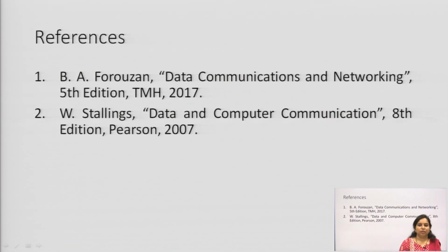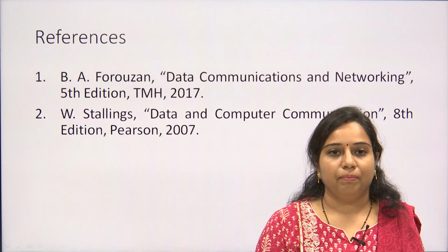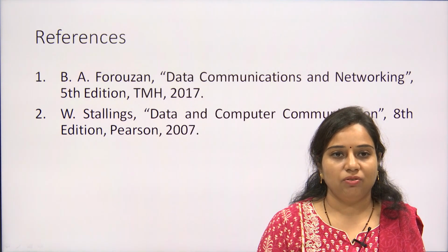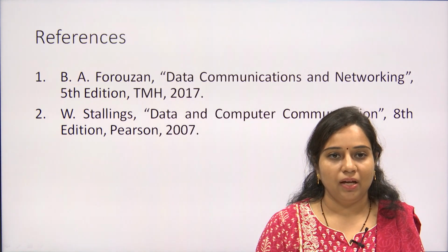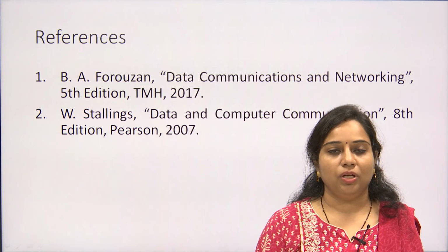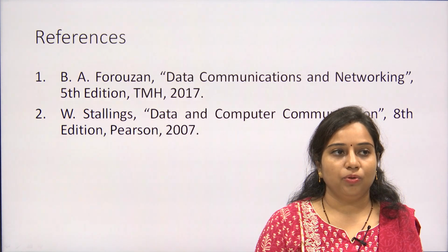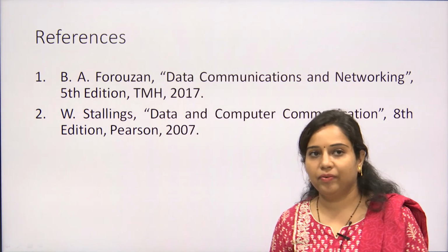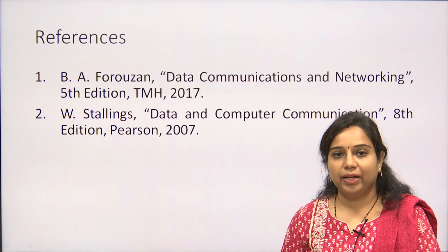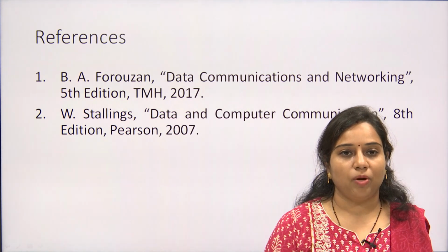So, this is all about the line coding that we have seen. Different types of line coding I have used, that is unipolar, bipolar signaling and polar signaling. In case of unipolar signaling, only a single voltage will be considered, either plus V or minus V, and for 0 it will be 0 voltage. The main disadvantage of unipolar signaling is that it is going to break the synchronization between the transmitter and receiver. If I am transferring 10 continuous 0 bits, it will break the connection between the transmitter and receiver, because the receiver will understand that the transmitter has stopped transferring the bits.